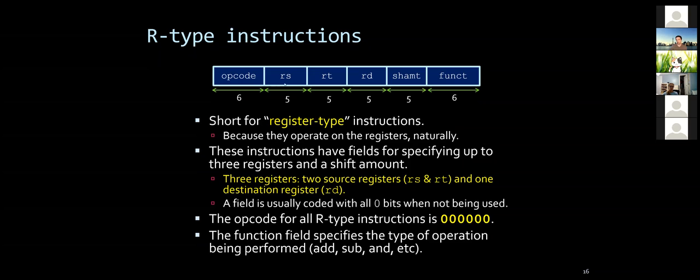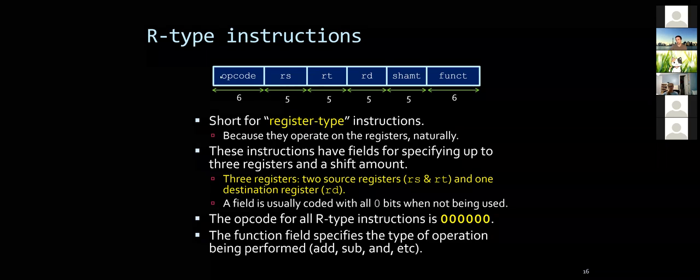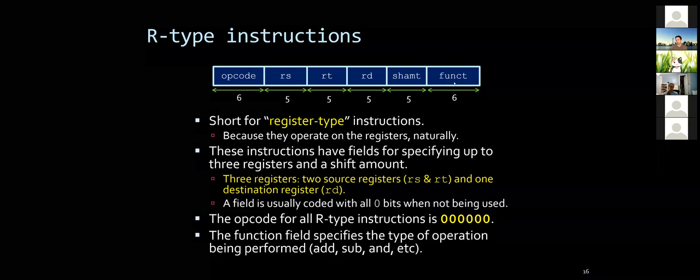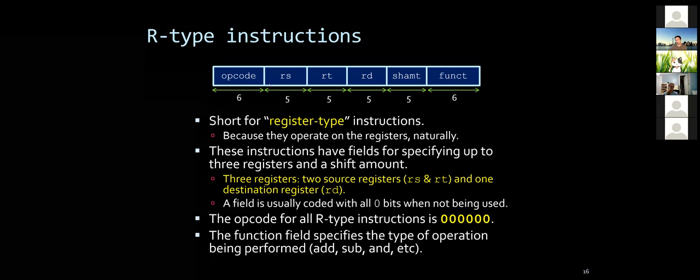I might want to have way more different instructions, right? Especially if you want to cover all the different math. So for the most common instructions that just operate on registers, I don't want to use those bits and limit other more fancy instructions. So I keep this functionality in here. So this is a part of the answer. I want to save the opcodes.